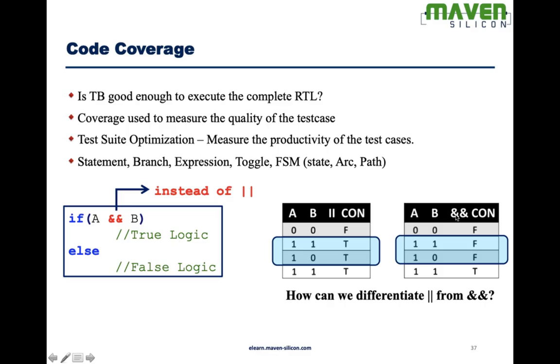That's where when you apply expression coverage, the tool is going to look at the expression. In this case there are two variables, so obviously it will try for all possibilities. 2 to the power 2, 4 possibilities. Here we are generating only 2 patterns, 0, 0 and 1, 1, so the expression coverage is going to be only 50%.